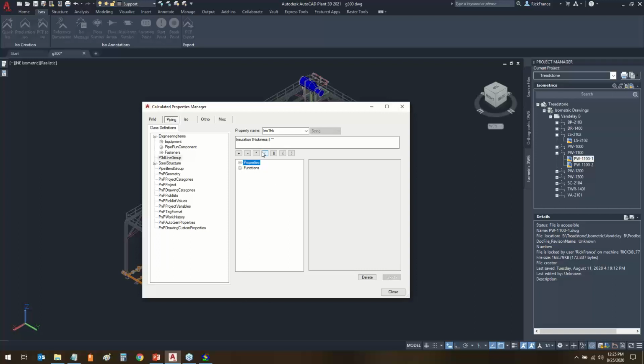This is all you have, but you can get a little better customization here. So it's something you may want to check out sometime. You can see there's different sections depending on what you're doing. These are the only 3 I need right now, though. I'm hard coding P141 for the file name, hard coding P141 like that for the drawing number, and then I've got my insulation thickness being created where it'll give me the 2 insulation with the inch symbol.